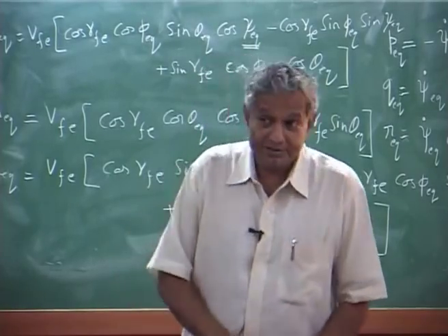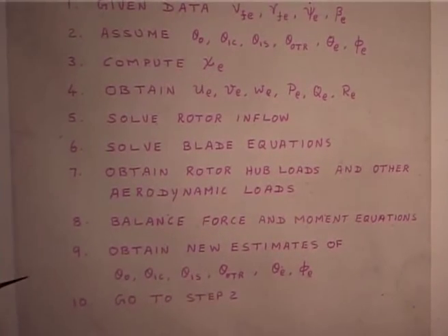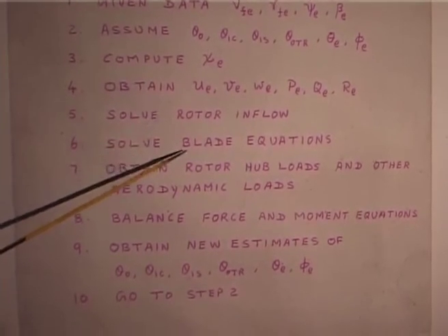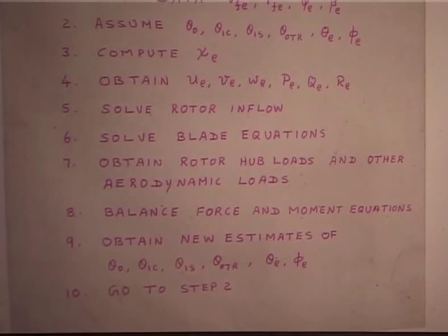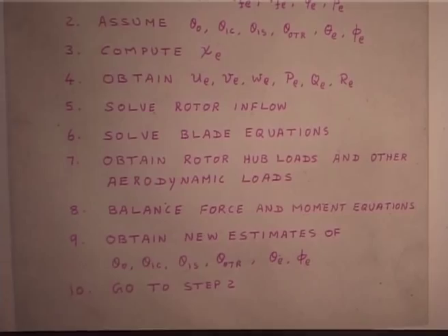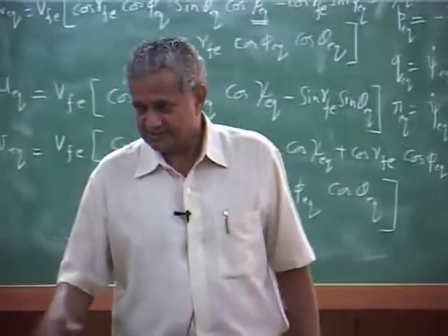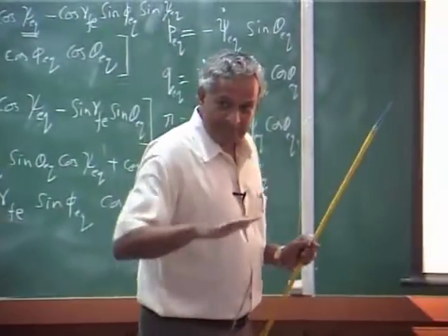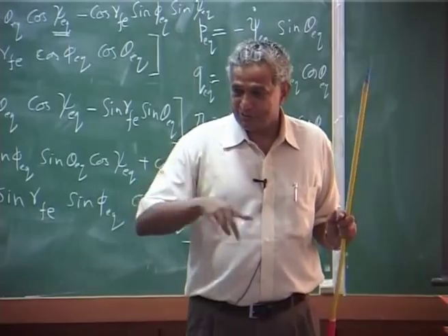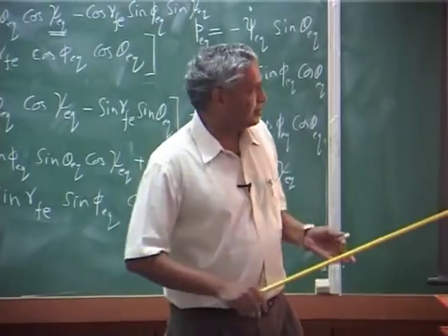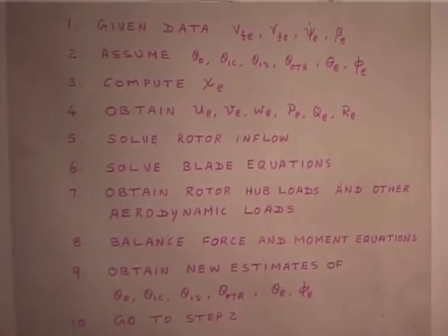And this is where in between you have to get the rotor inflow, please understand. This is also an equally complicated problem, because rotor inflow is related to rotor thrust. Okay. So, you can have various types of inflow models, dynamic wake model, and we have incorporated something which is Dries model you can put, but that is again a constant, even though it varies along the radial and azimuth, it does not vary with time. So, you can have different types of inflow models.